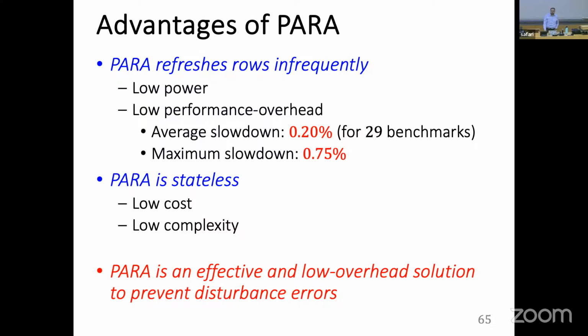I will show some results as well. Some data from 2021 shows that in a 64-bit data word, you can have more than 7 bit flips, which is too much for the ECCs deployed in today's systems. So they are also vulnerable to this. Is that okay? Good.